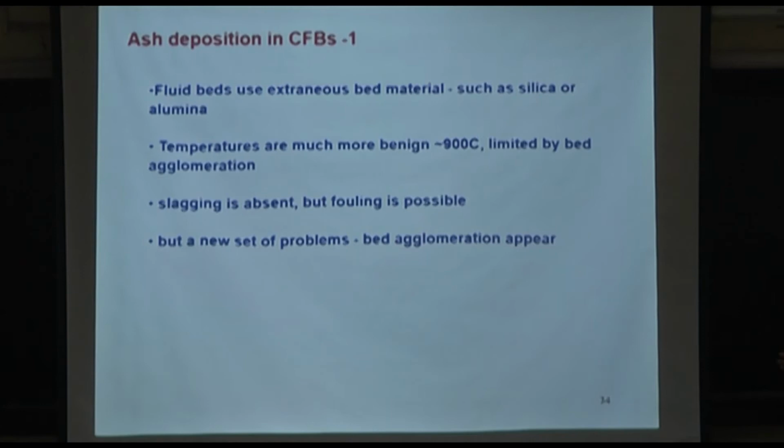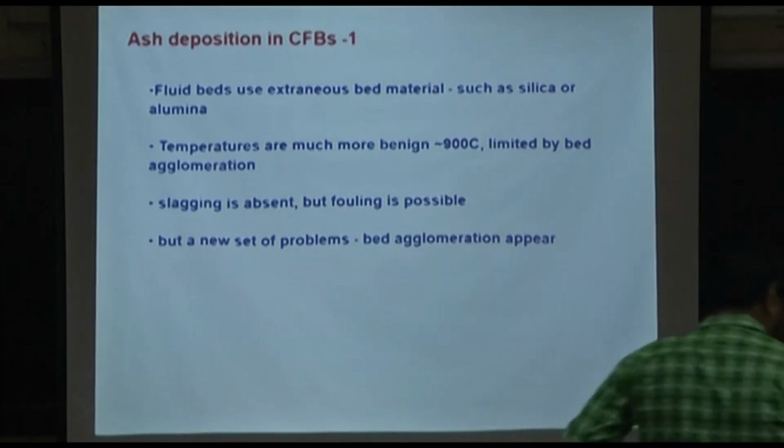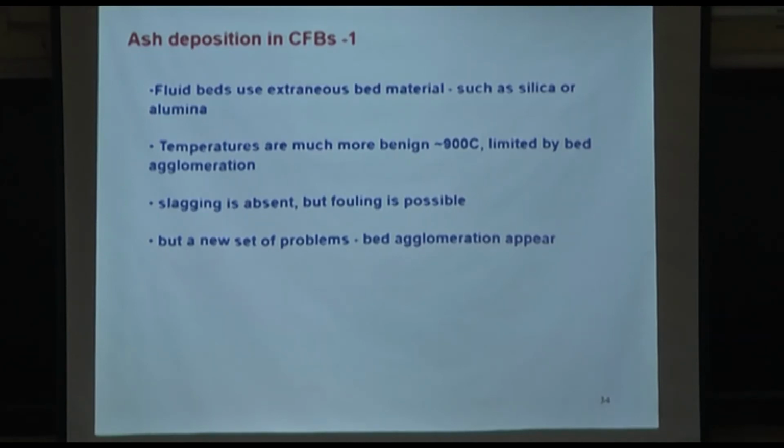Slagging is decidedly absent because there is no flame and there is no high temperature, 1500 degrees centigrade, near the burner zone. But liquids can still form, but we'll come to that. A new set of problems, bed agglomeration, appears in fluidized beds.